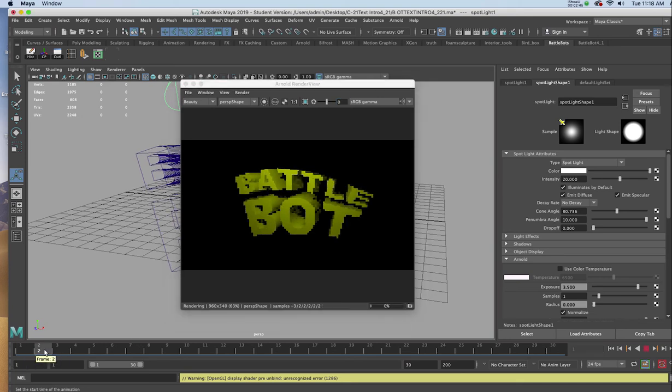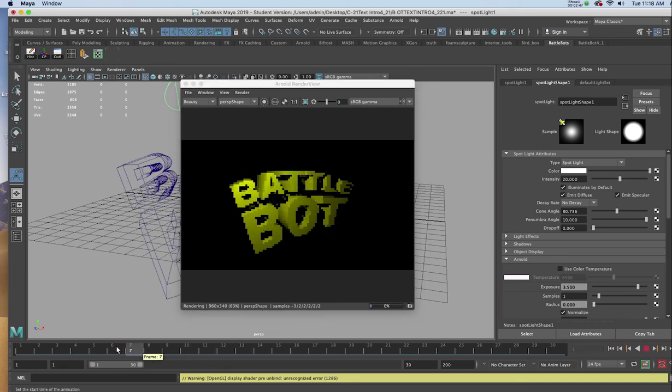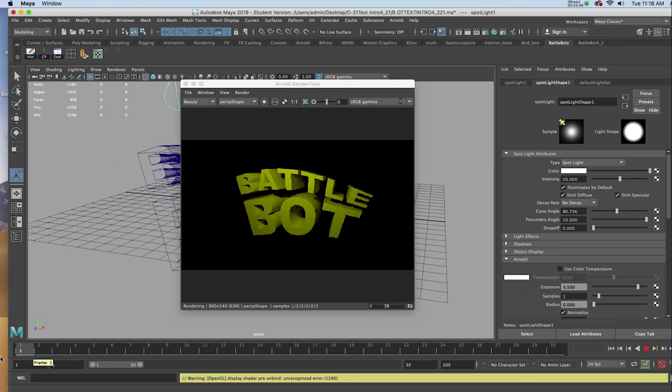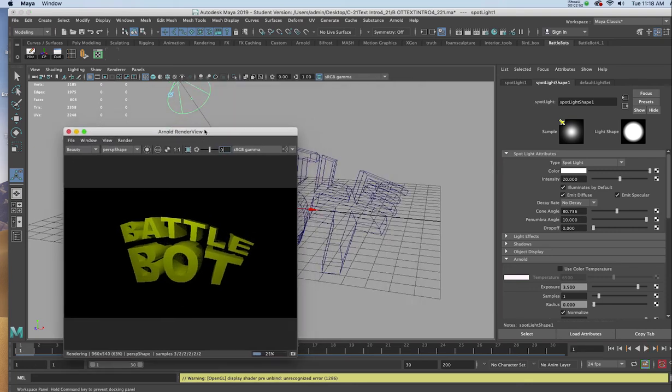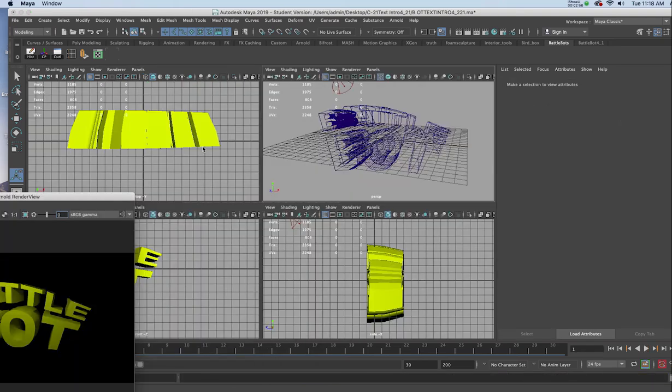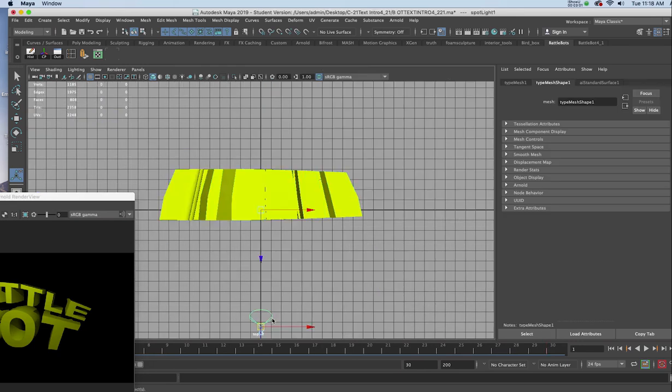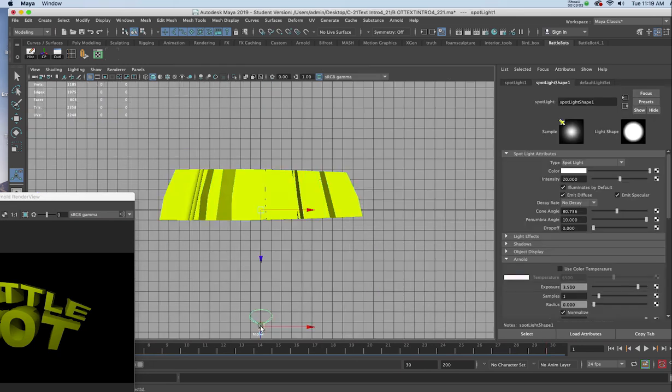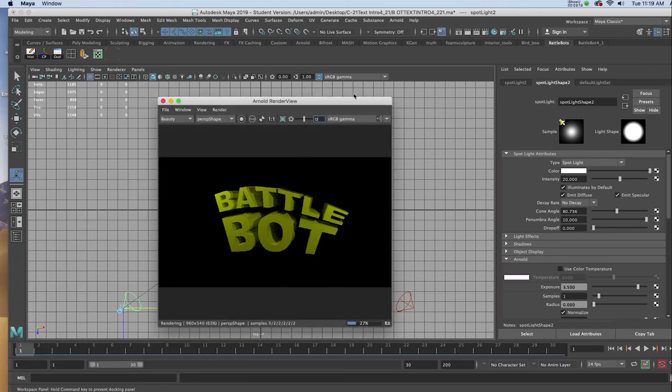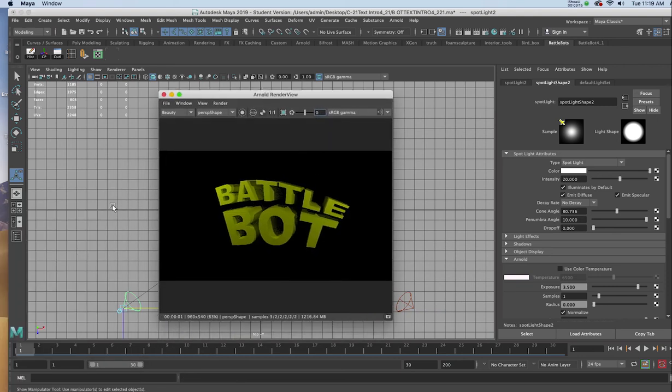Now if this were to rotate through, it gets dark on the sides. The first thing I'm going to do is go to my top view, and in my top view I'll select the light icon, making sure I've hit T. So I'm in the edit mode. I'll drag it over to the right hand side. In my top view I'll hit Command D, and then I'll drag the duplicate light over to the other side. So I'm starting to see something like this.